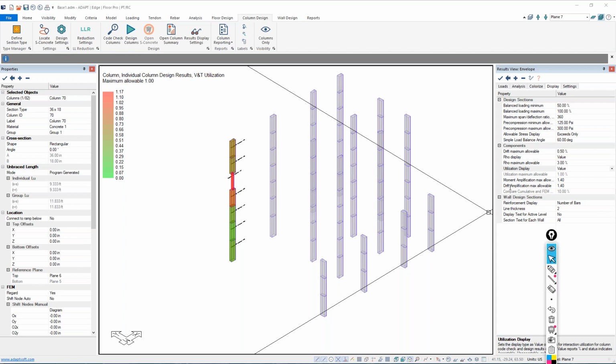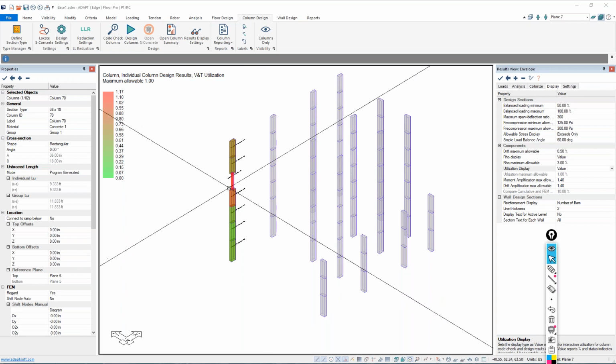The question is, is there a way to do small p delta? The answer is no, not at this time. That's a short answer. The question is like creating small columns with intermediate nodes. And you could manipulate the program to determine, if you had intermediate nodes, you actually don't have to create a small column. You could discretize the column differently.